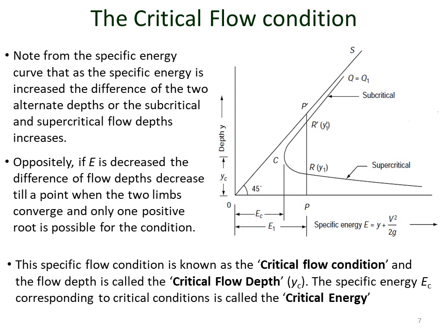Only one flow depth is possible. This particular condition, at which for a given discharge only one flow depth is possible, is where the specific energy is minimum.